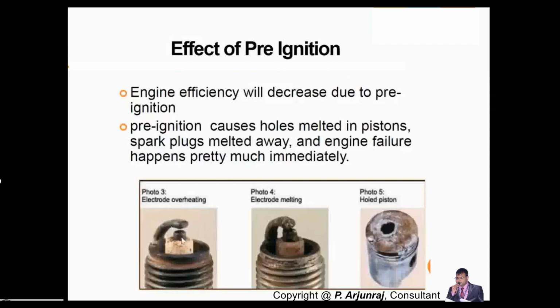The spark plug has the electrode, and that electrode will get overheated because of the ignition, and finally it will lead to damage of the piston, and ultimately engine failure. So this is how the piston looks when you get the pre-ignition.